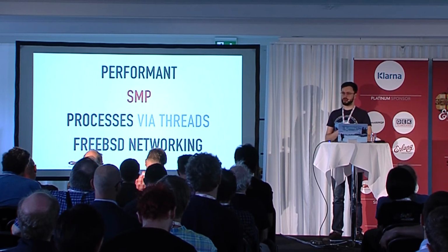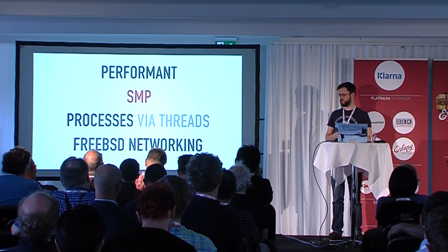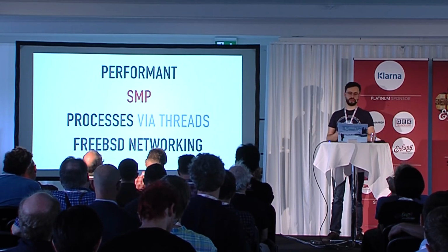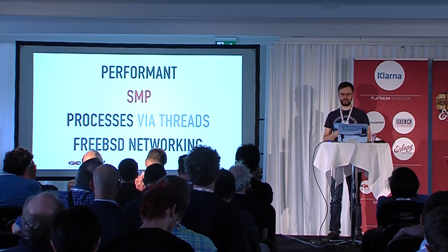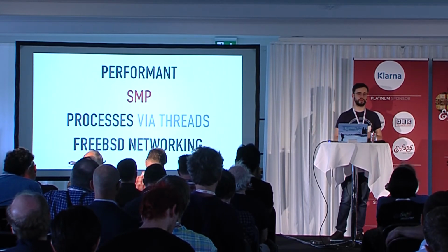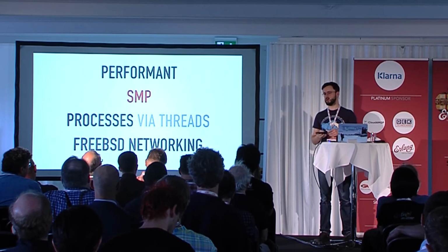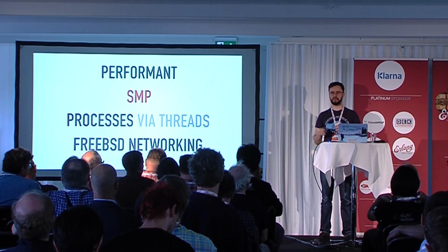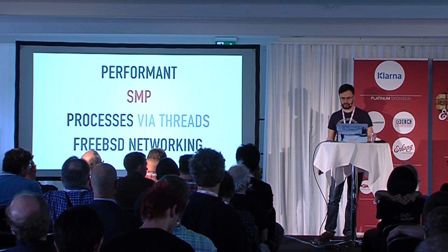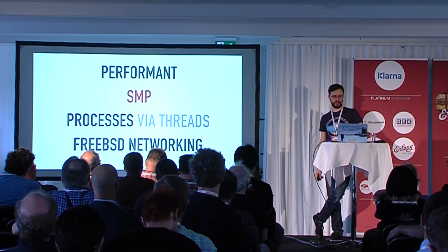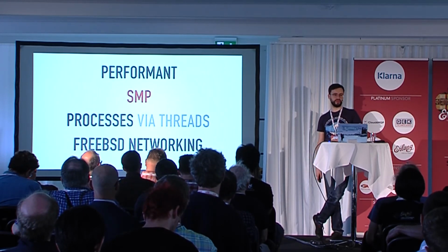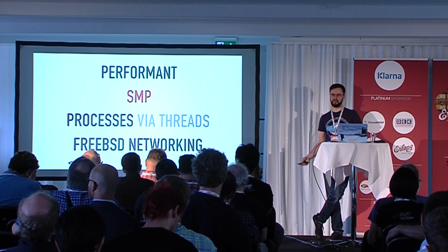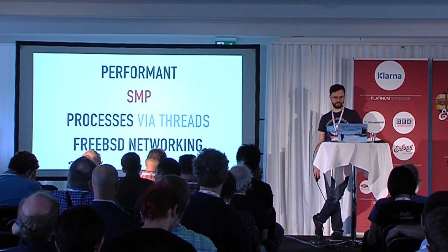It has SMP support, which is nice because Erlang supports SMP, and if we go for a multi-core processor, we could use this, so that's very nice. And it supports different networking stacks, but among others, it supports the FreeBSD networking stack, which means you can compile RTEMS together with the drivers from FreeBSD, so you can get things like Ethernet, Wi-Fi, USB, things like this. And that means that we get lots of drivers for free, and they're fairly advanced high-level drivers, so you can do a lot with them, and it's a nice fit for Erlang, which is also a high-level language.